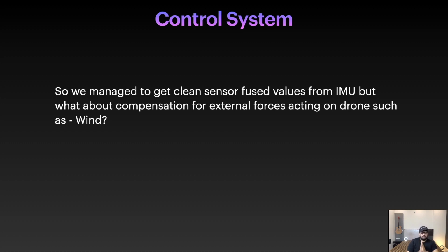And again, wind is just one external example that you would need to compensate if you want a stable flight. But what about some internal factors? Let's say you are building a quadcopter, you are using 4 motors, exactly the same motor, but since it's mechanical, it cannot be exactly the same. Maybe some motor has more RPM than the others. I'm not saying it would have drastically more RPM, but let's say 100 RPM more because of, let's say, manufacturing defects, or it is a bit smoother.